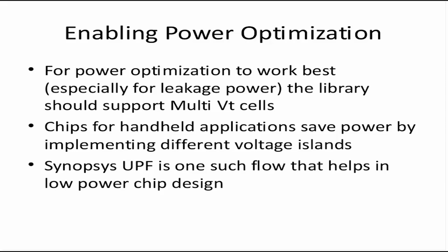So what such complex chips try to do is that they implement different voltage domains. Different parts of the chip work on different voltages. Even if they are working on the same voltages, they have different supplies, so that one part can be switched off when not in use. This saves a lot of power. What if your video encoder or video decoder is on even when you're talking on phone?